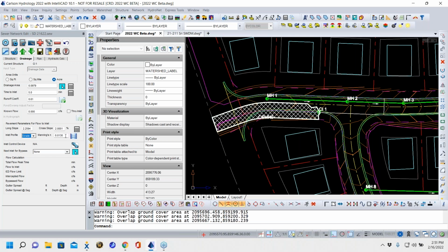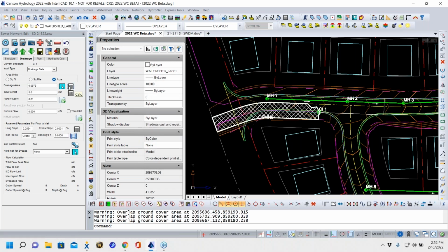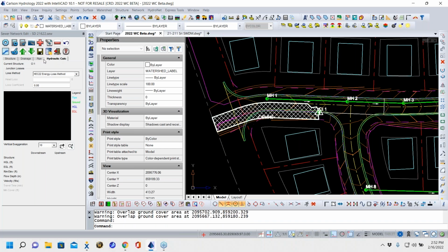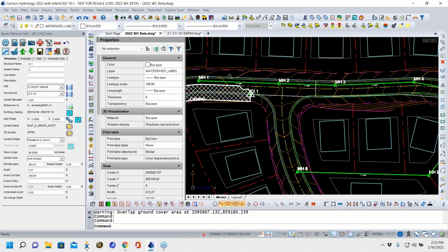And there's my pipe mainlines in. If you click on the outside the library, you can go to the library where the mainline ends are and just select the one you want. So now we don't have a pipe yet, so I can't go look at the pipe. We don't have much on the hydraulic calc yet. So now what ends up happening is we've told it everything we can about curb inlet one.